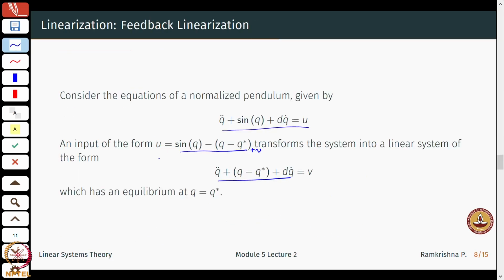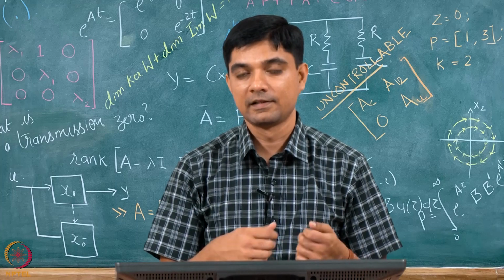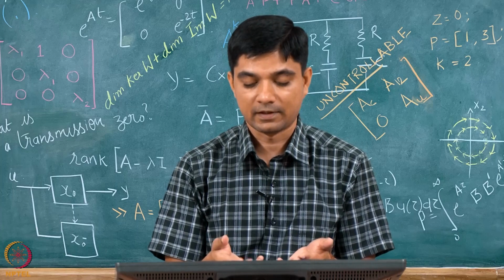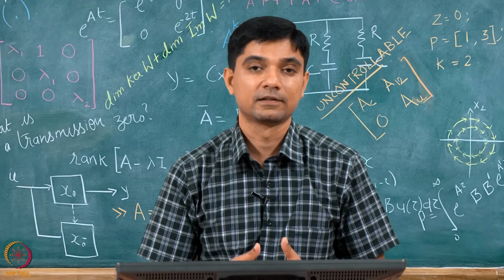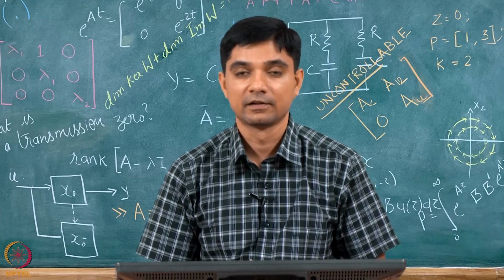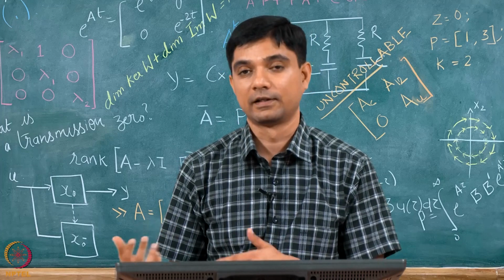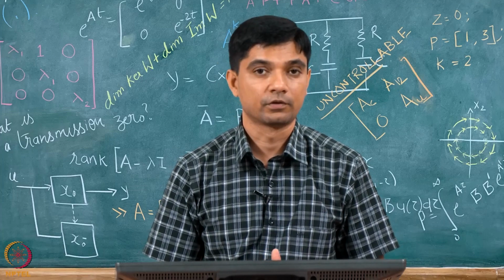Similarly, what I did essentially here is that I used a state feedback, a nonlinear function of the state, to kill the nonlinearity. The nonlinearity here comes from the sinusoidal term. This is also called feedback linearization. Now, can I do this all the time? Mathematically, here I am just adding a sine term to the input and the nonlinearity disappears. Can I do it all the time? Again, the answer is no. There are some conditions that the structure of the system should satisfy in order to accomplish this feedback linearization. There are several nonlinear examples in literature which cannot be feedback linearized. Of course, that is not our point of interest.